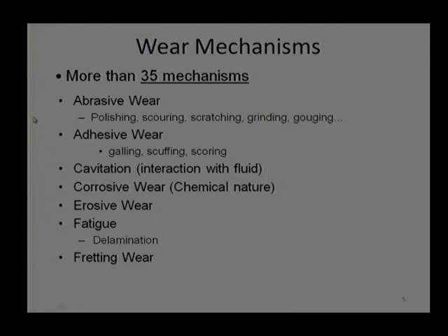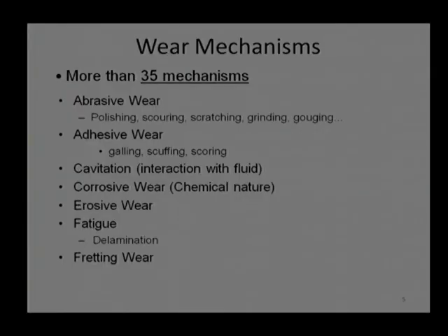There is another kind of wear which we know, erosive wear. It happens again because of liquid, or high velocity liquid, or high velocity particles also. Particles are generally more common to cause erosive wear. A typical example is fly ash. If high velocity fly ash impinges directly on the surfaces, it will cause excessive wear. Another wear is fatigue wear, and one category of fatigue wear itself is delamination.